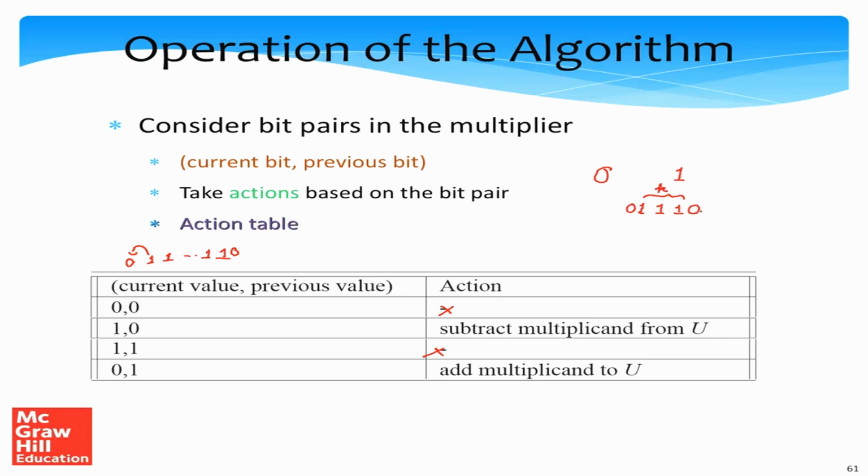Then in the case of an iterative multiplier, we are essentially doing k additions, which was a lot of work. What we are saying is that it's not required. What we can instead do is that we can do one subtraction at this point and one addition at this point that is equivalent to actually doing k additions, because it's a simple sum of a geometric series. So instead of adding k numbers, we can essentially do one subtraction and one addition and we are done.